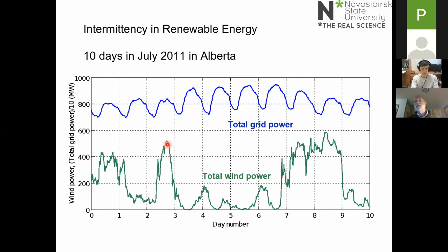And so I think you begin to see a couple of things from this. One is that when you have a significant amount of renewable energy on an electricity grid, then you need complementary generators. You need backup generators who can be turned on and turned off very rapidly.